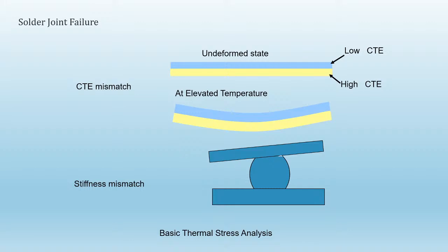So the fundamentals of solder joint reliability, we're specifically going to focus on a narrow aspect of it. We're going to look at solder joint reliability for BGAs due to thermocycling. Solder joints have a few different failure scenarios. Thermocycling historically has been the one that causes the most failure. High power chips tend to generate a lot of heat.